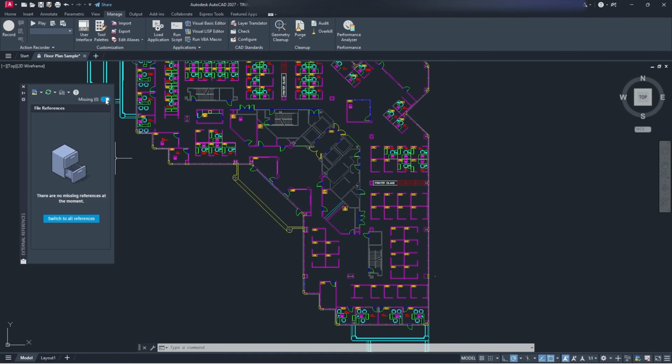So normally when a referenced file is renamed or moved, any drawing that is dependent on that XREF can no longer be located because its path changed. With that said, you used to have to go through for each missing reference and load it properly into AutoCAD, and it just creates an absolute nightmare. This is going to absolutely help you a ton if you use XREFs because you can literally just click a few buttons, find the new thing, know exactly where it is, and it's done.